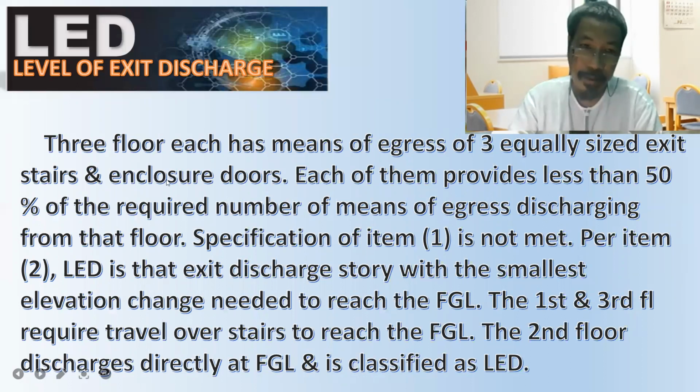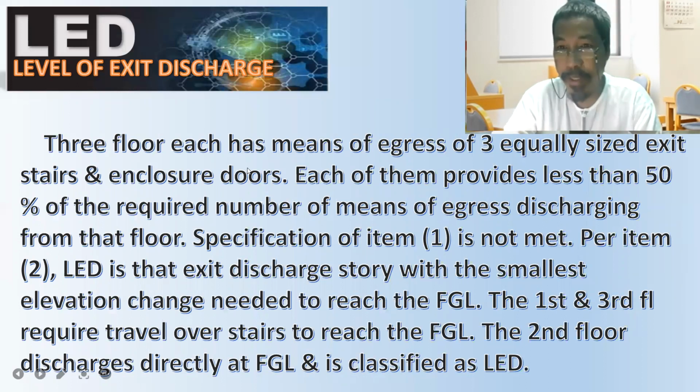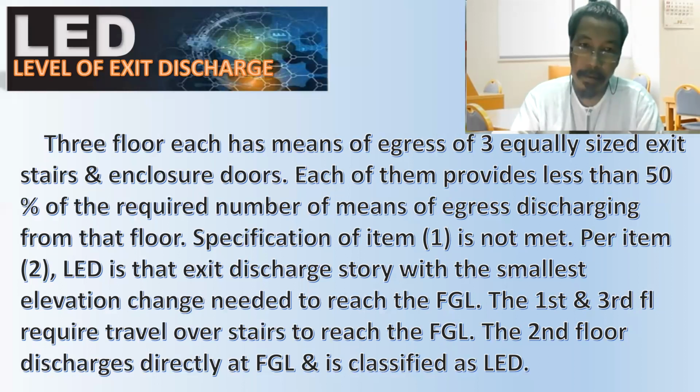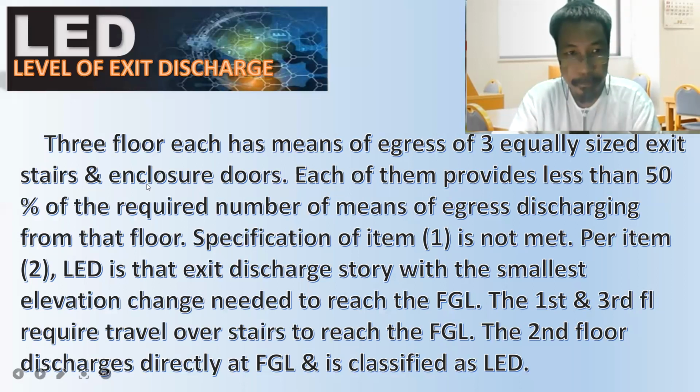We did not see it in the picture, but for the exit to be considered as exit discharge, this exit should have enclosure doors, and each of the exits provides equal or more than 50% of the required number of means of egress discharging from the floor.